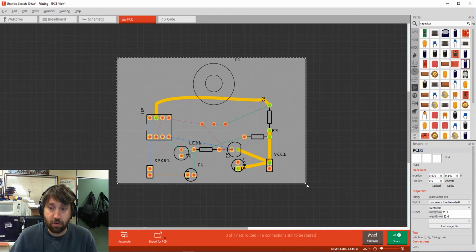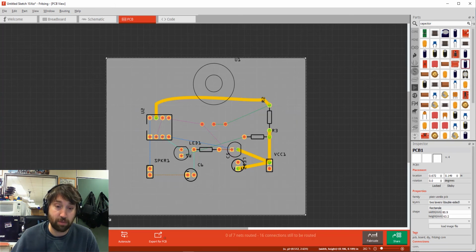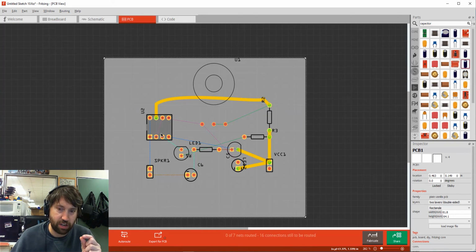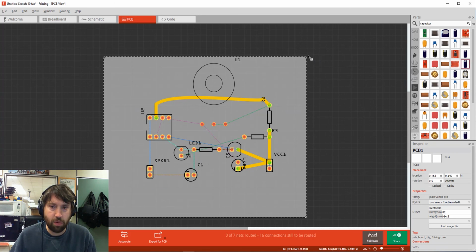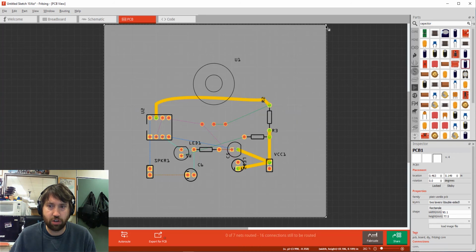But because you're carving this on a particular CNC router, the Carvey, a part of the material that we will place into it won't be able to be carved because of something called a smart clamp. And that's what it uses to detect where the top surface of our object is, which is important. If you don't know where the top surface is, making a very, very shallow cut in an object isn't really possible. So essentially, the first inch or so of our PCB material won't be carvable. So to compensate for that, we're going to take the overall contour of the PCB, and I want to pad it by about an inch.